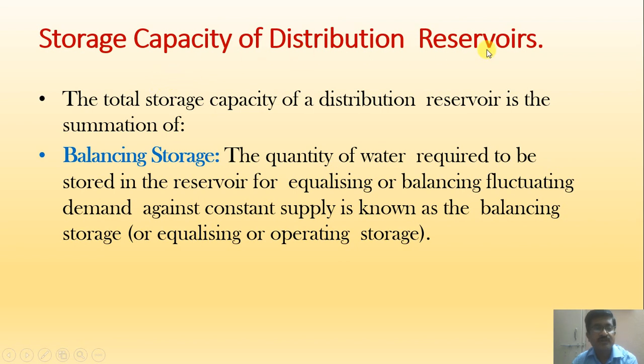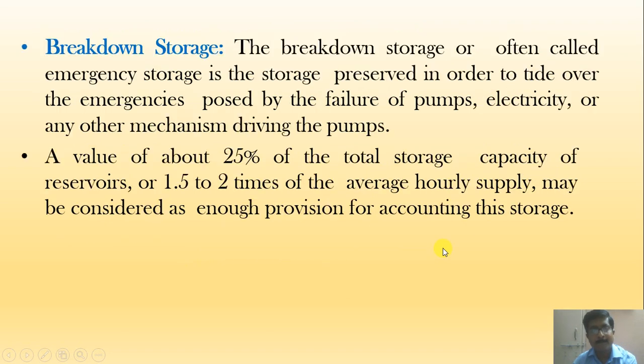Storage capacity of the distribution reservoir, we have also seen which factors affect it. The total storage capacity of a distribution reservoir is a summation of the balancing storage. The quantity of water required to be stored in the reservoir for equalizing or balancing fluctuating demand against constant supply is known as the balancing storage, or equalizing or operating storage.